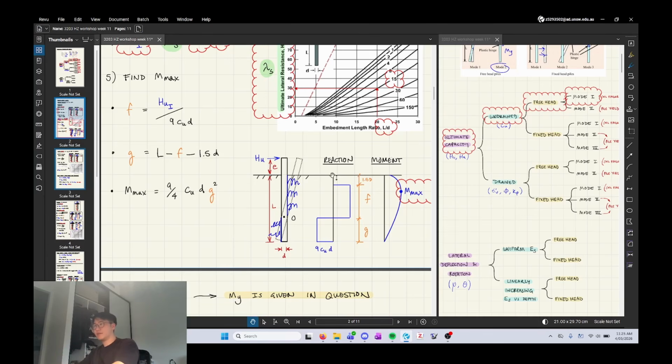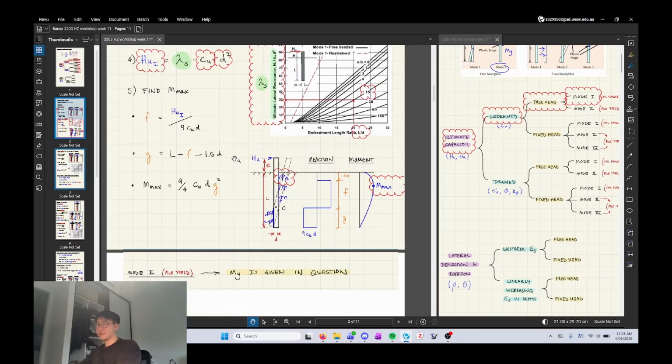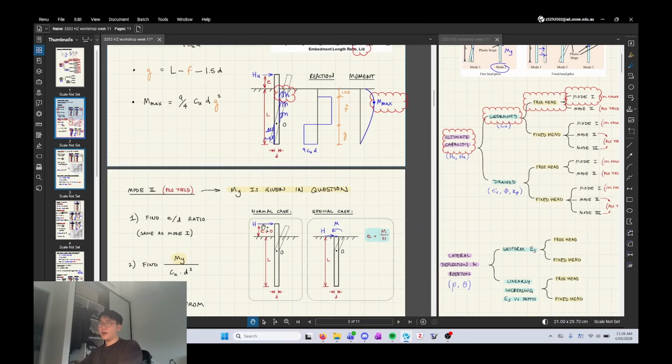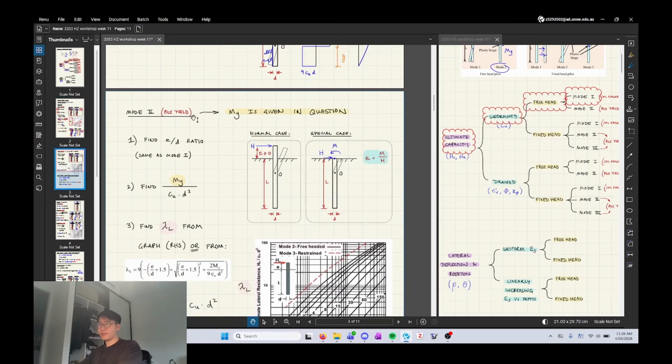And then there's also this portion due to soil cohesion, which makes it so that the soil's in tension. And so we don't give it a reaction. Here you'd almost have a negative reaction at the spring, so it'd be in tension. So we don't consider that portion due to the soil's stickiness, clay's stickiness.